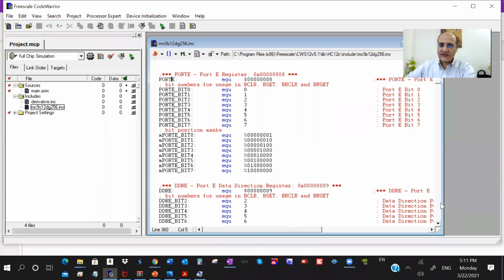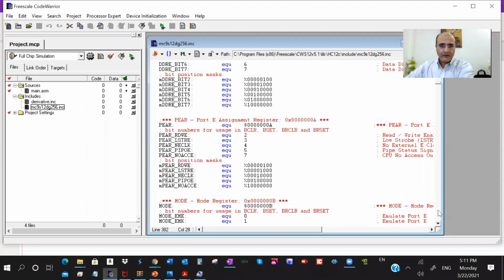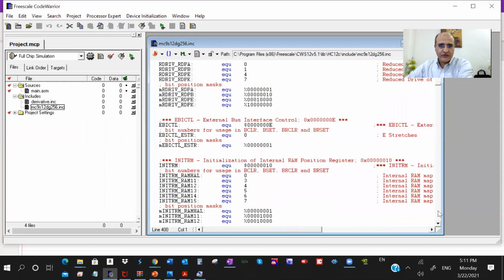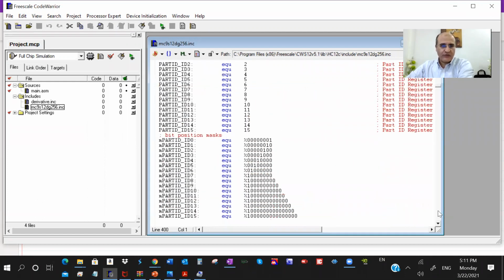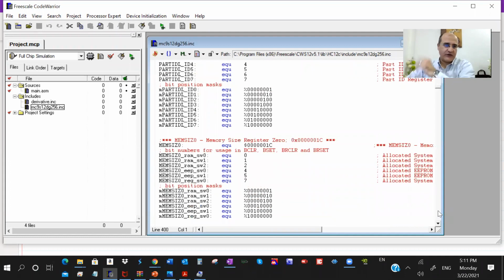These are dealt with as memory addresses, and they're really located in the SRAM, and mapped to the actual ports. They're given addresses. And you don't have to remember these numbers. The include file here just gives you an option to use the word. So port B, you just say port B. You don't need to remember that it is address whatever.